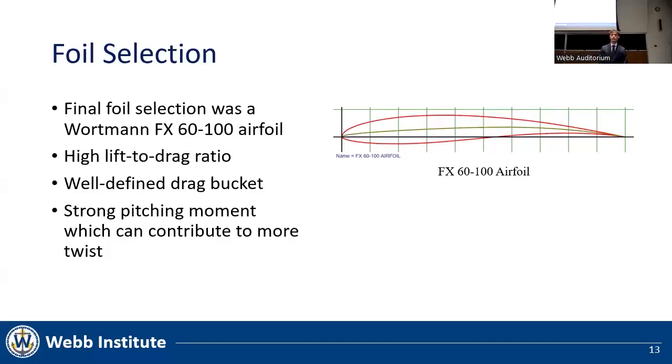While searching for an asymmetric foil section to use for this analysis, we had two main criteria. Most importantly, we wanted to choose a section that had high performance at our operating speed of 4.4 meters per second, meaning a high lift to drag ratio at relatively low Reynolds numbers. The second characteristic we looked for is a drag bucket, where the drag drops significantly within a range of angles of attack. Our thought process for this is if the foil can tap into this angle of attack range while twisting, the performance gain may be even more exaggerated.